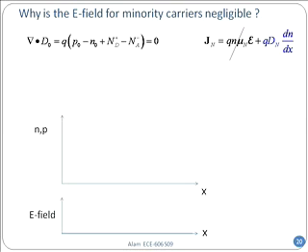So what's happening? You remember that in equilibrium, if it is a homogeneously doped sample, as was the case for the example I just told you about, the electric field will be zero, because n naught and p naught and Nd plus and Na minus will conspire together to make the electric field locally at every point equal to zero. So that was not a problem. Now, remember that this was an acceptor doped region, right? That's how we set up the problem. In an acceptor doped region, I can say that p naught is equal to Na, right? In equilibrium, I can say that.